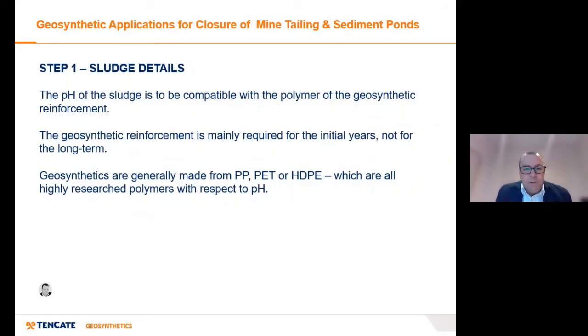Another detail we should determine with the sludge is the pH, and this is more just a check for short-term durability. So with a mining pond closure, you might be dealing with environmental regulations that start talking in hundreds or thousands of years, but the geosynthetic reinforcement is not required for that long. So the geosynthetic reinforcement is there for the initial years in terms of durability, and is there mainly to take